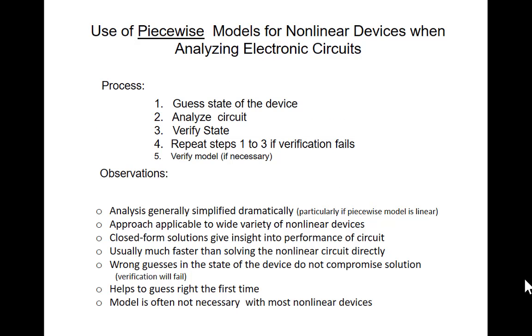So one thing, how can you assume that an I source is one femtoamp? Oh, you don't have to assume that. When I said IS is equal to 1 femtoamp, that has to be obtained from the characteristics of the diode. There's nothing predetermined; that's set when the manufacturer made the diode.